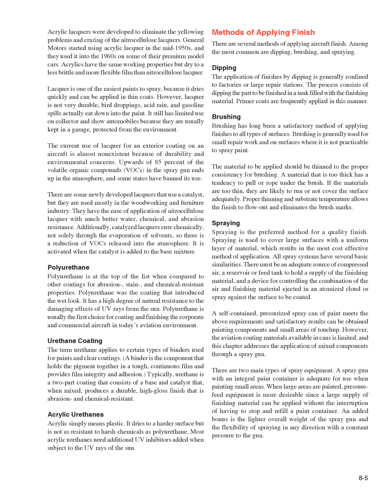Lacquer is one of the easiest paints to spray, because it dries quickly and can be applied in thin coats. However, lacquer is not very durable. Bird droppings, acid rain, and gasoline spills actually eat down into the paint. It still has limited use on collector and show automobiles because they are usually kept in a garage, protected from the environment. The current use of lacquer for an exterior coating on an aircraft is almost non-existent because of durability